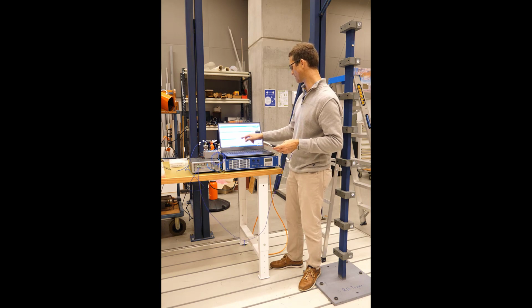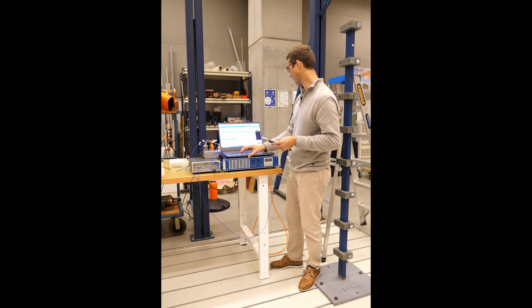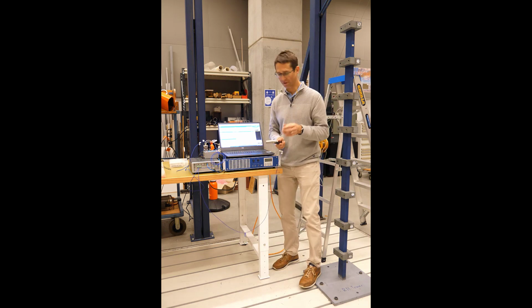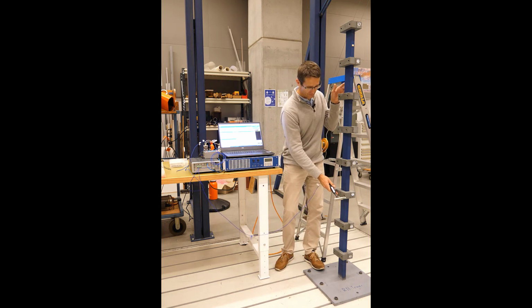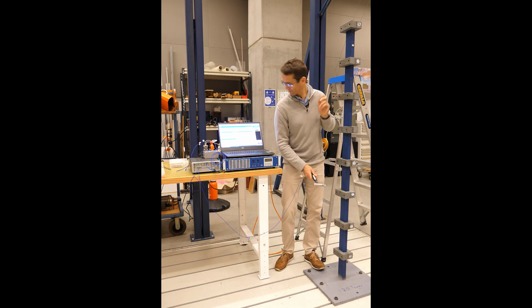In this case, my coherence is not quite as good as it was for the previous FRF. It's not too bad. There's a few drops in the coherence, particularly around the anti-resonances, which I'm not too worried about. I'm more worried where I've got poor coherence at a resonance, particularly this low frequency here. It's quite challenging to get good coherence around that first and second low resonant frequencies, and that will be evident also in our mode shape modal analysis processing subsequently. The shapes will be noisy.